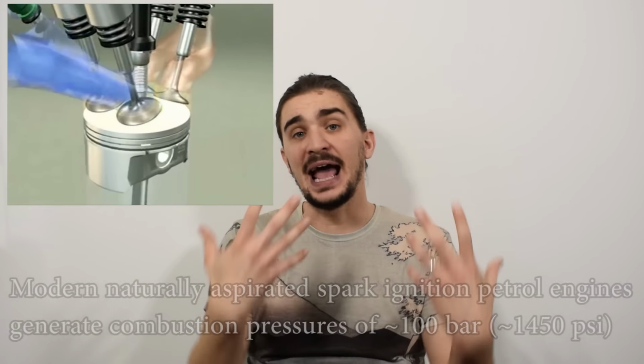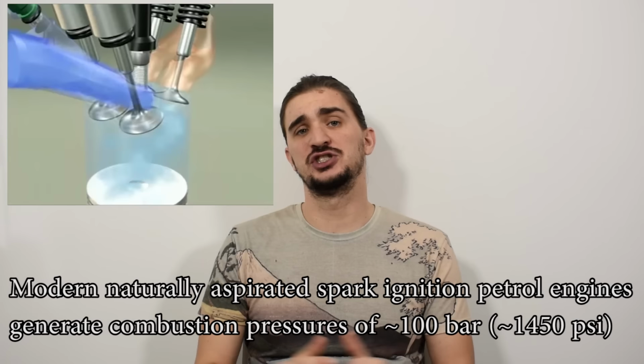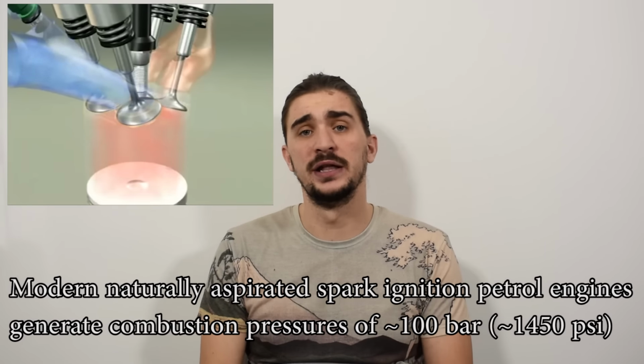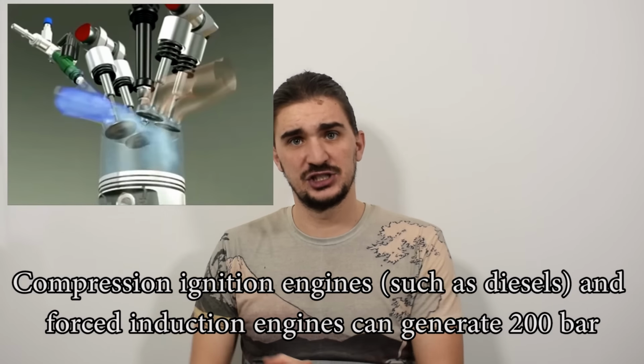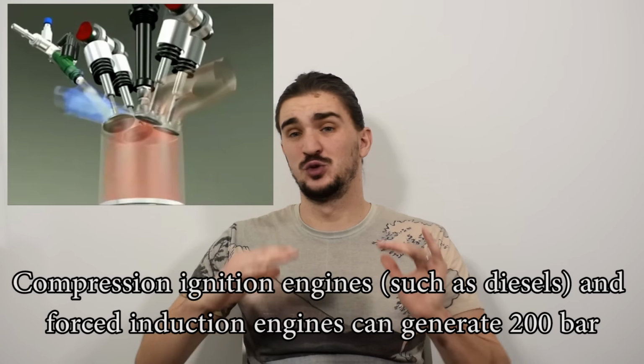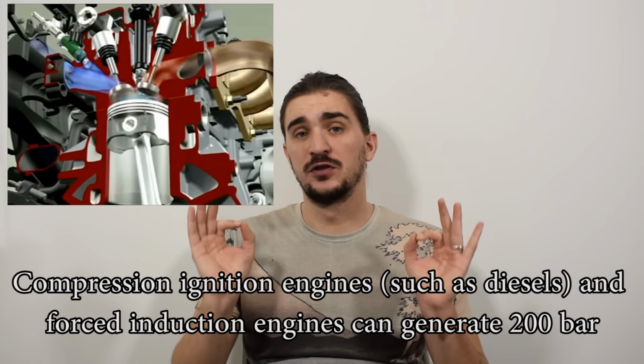So now that we know what a crankshaft is and what it does and what its parts are, we're going to find out about the forces acting on the crankshaft. Now, the most obvious source of forces acting on the crankshaft, of course, comes from the combustion generated by an internal combustion engine. Modern spark ignition petrol engines that are naturally aspirated usually generate combustion pressures in the neighborhood of around 100 bar. Compression ignition engines and forced induction engines usually generate twice that, around 200 bar of combustion